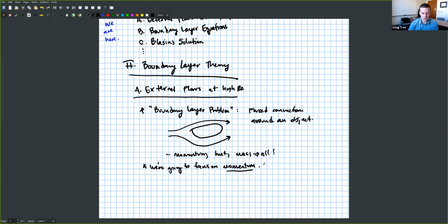Okay, so it's the foundation, and I'll put BLPs, boundary layer problems. You're going to need that velocity field when you plug it into, if you remember, the heat transfer equation, there's the big dV/dt, right? Or excuse me, like dCA/dt. I guess that's mass transfer, which has the partial CA dt plus V dot grad CA, right? And that we're going to need to get. So if we're going to do a mass transfer problem, we need the velocity first, to be able to do that.